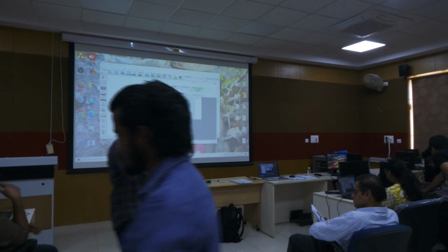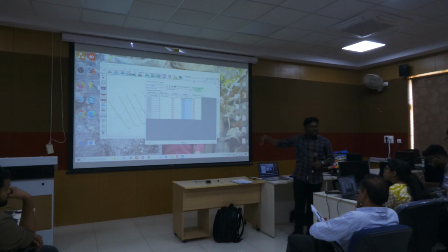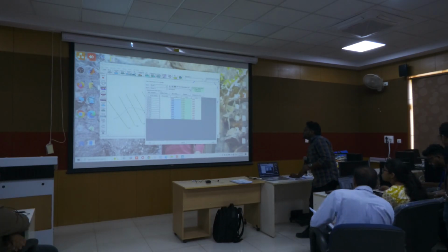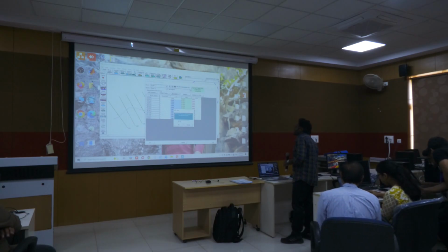So next step. So this is for the main channel. In the left bank and the right bank, same. Assume that it will have more roughness. So assume 0.06.